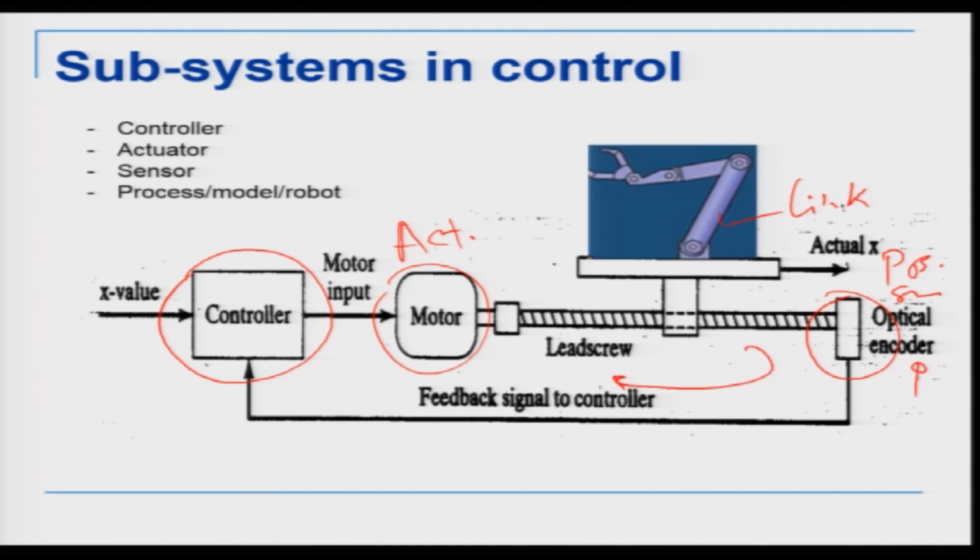So in the last class we also said that if you look at the dynamic equations, the dynamic equation tells us that the joints are all coupled with one another, because of which the motion of one joint affects every other joint. That means every joint affects every other joint in the system, and this is what we call a coupled system. So in reality a robotic system is a nonlinear coupled differential equation, the equation of motion, and this basically says that the system is coupled in nature.